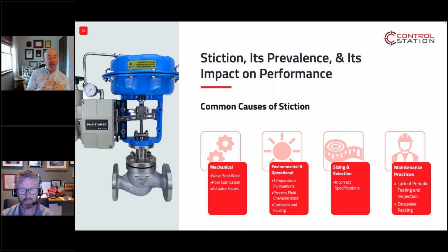If it's particularly corrosive or sticky, those kinds of fluids can have a significant impact on the performance of the valve, and also depending upon the type of valve that you have. If you have a globe valve, it's a little less resistant or affected by some of those kinds of things, but other types of valve, ball valves and so on, may be more susceptible to certain types of stiction and corrosion as well.